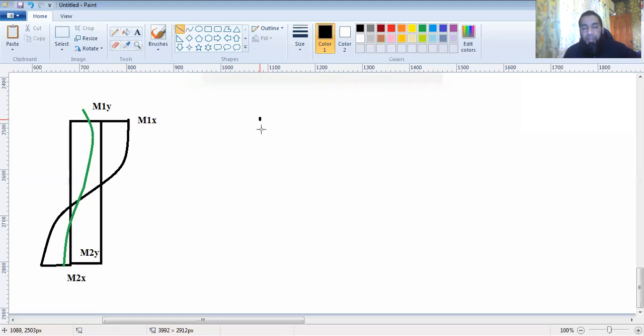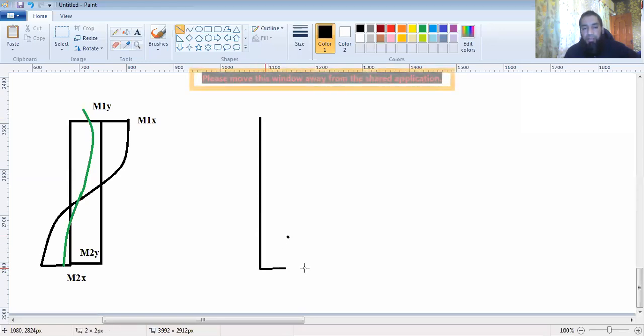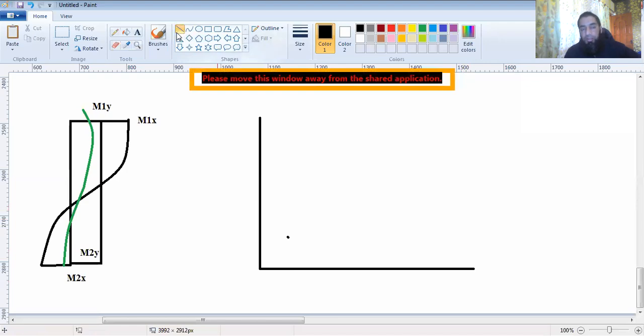So the PM interaction curve in this case, when you have a biaxial eccentricity acting in two directions, it's not a curve, because it's through the interaction of two different planes, one in this direction and other in this direction.